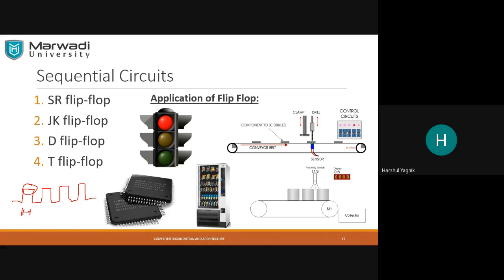Whatever is the input, okay? Suppose set and reset, any input is applied, but the flip-flop will not update its value as soon as the signal is applied. Flip-flop will update its value when the triggering happens. And here, if it is chosen to be logic high level triggering, then it means that the flip-flop will update its input value only when the clock signal is logic high. Is that clear? Yes, sir.